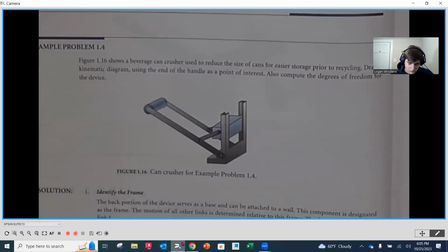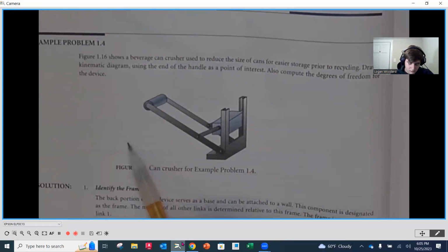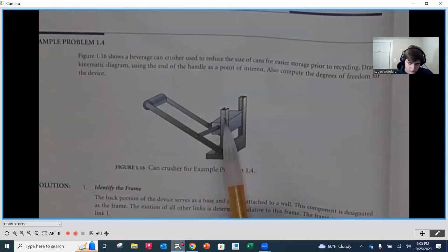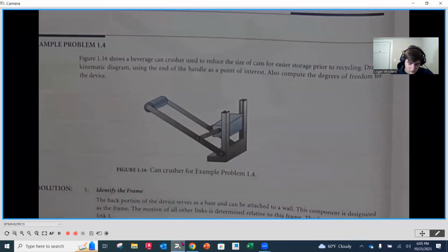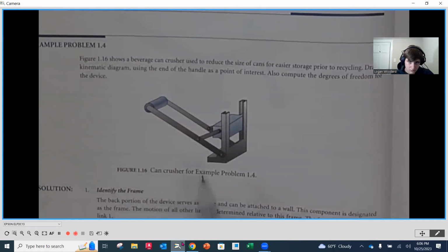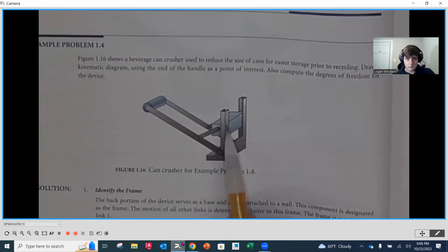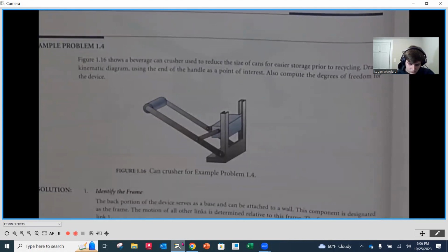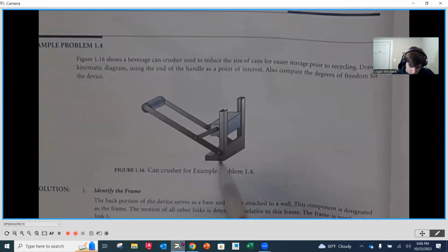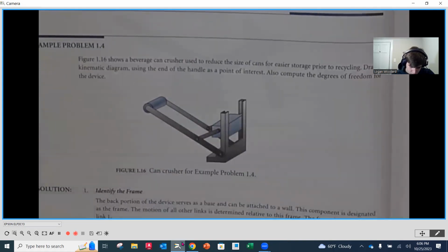And then as we pull down on that crank, or that handle, this slider is going to move up and down. When I pull down on the handle, it's going to go down. When I release it and I put it back up, it's going to then go up, right? Okay. Where's my frame on here? There it is. It's actually the whole L here. This is one continuous piece, but we're not going to show it as one continuous piece. We're going to show a connection to the frame with our handle, and then we're just going to show a vertical line, random length, for our slider.